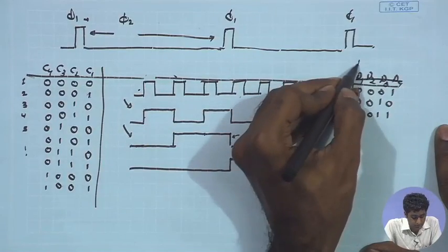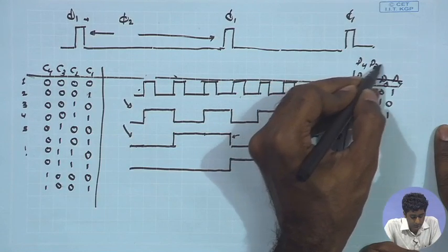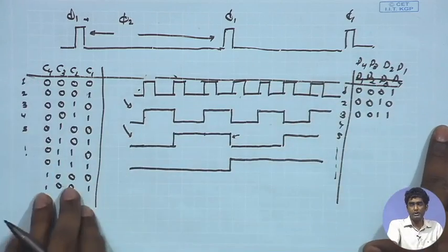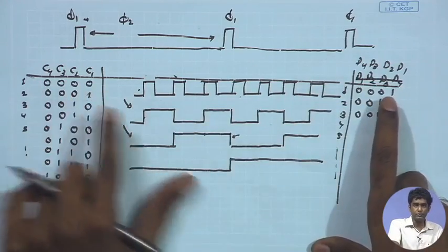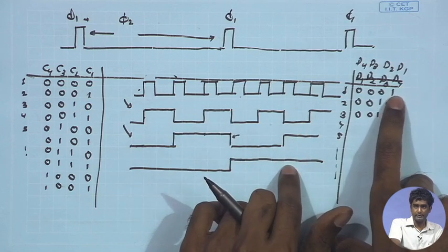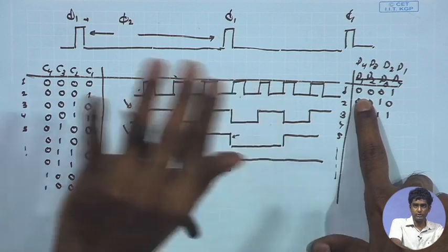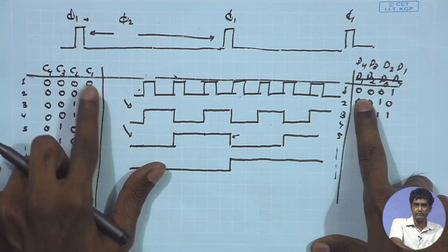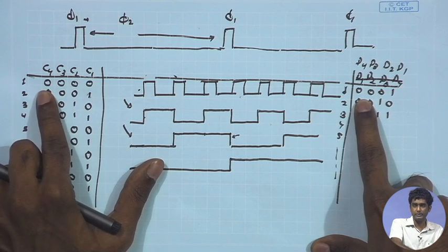the numbering is just opposite. So, I should just follow that convention, D2 and D1. So, C1, C2, C3, C4, D1, D2, D3, D4. So, if I make sure that the D input for the next cycle is 1 0 0 0, then of course, at the next negative edge of the clock, the flip flop will be changing state, the C1 will be going from 0 to 1, others will be remaining 0.